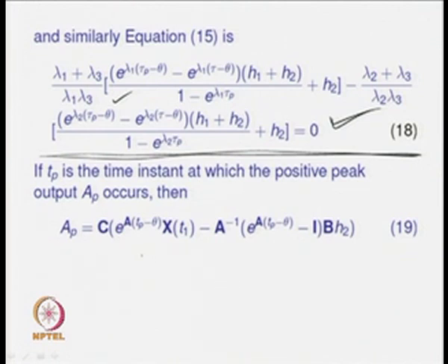We have seen the peak amplitude A p and another amplitude A v. Expressions for these 2 amplitudes are to be found, so that we obtain 4 analytical expressions to estimate at least 4 unknowns associated with the transfer function model.